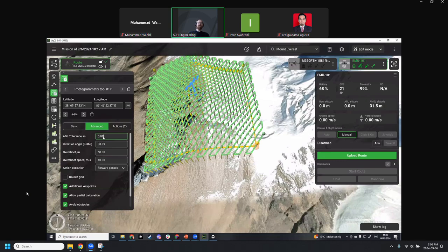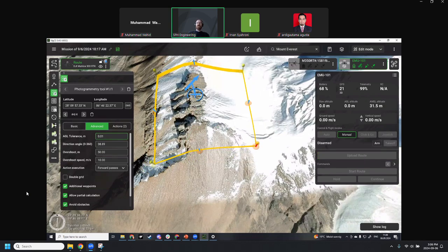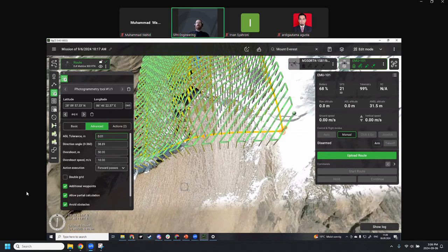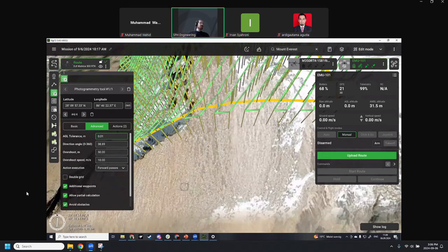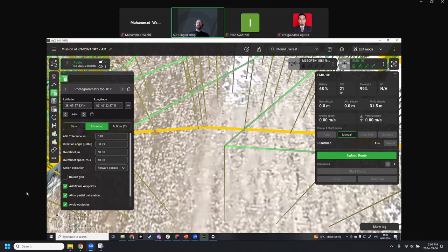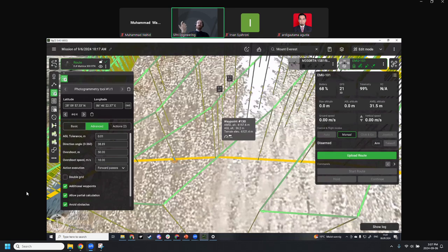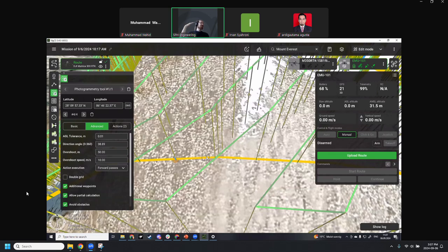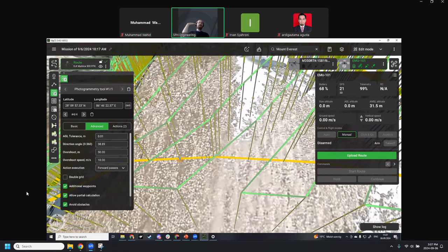So, for example, here's an AGL tolerance of 1 centimeter, and okay, the number of waypoints isn't so drastic, but because of the nature of how a drone works, for example, with these 3 waypoints, you may introduce issues. We have a specific speed set on these waypoints. Every waypoint has a flight speed of 5 meters per second. Once it reaches that waypoint, it cannot get to such a speed going to the next one.